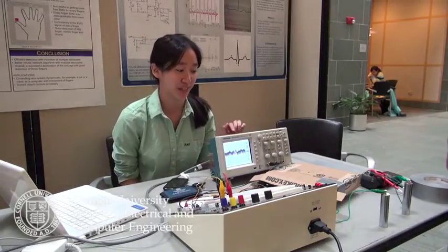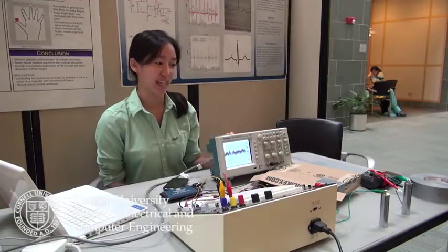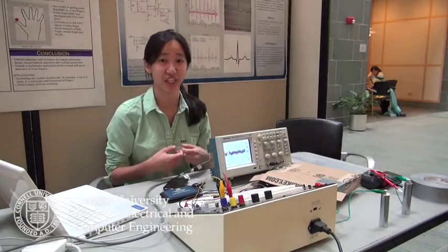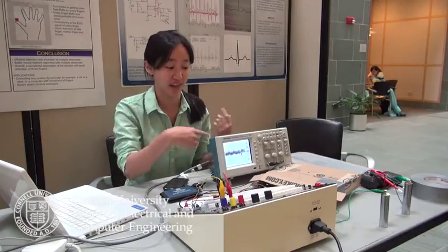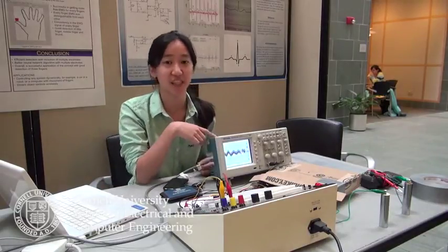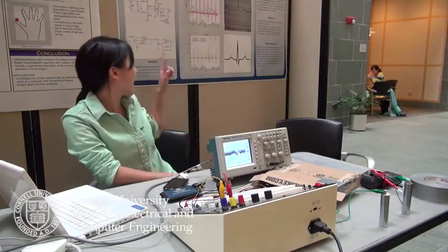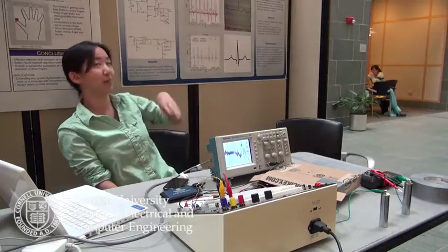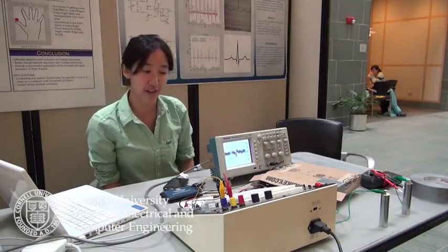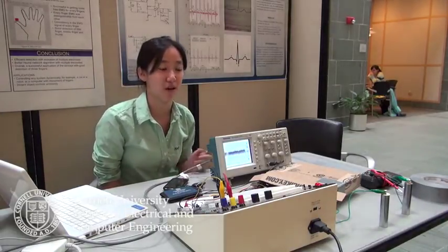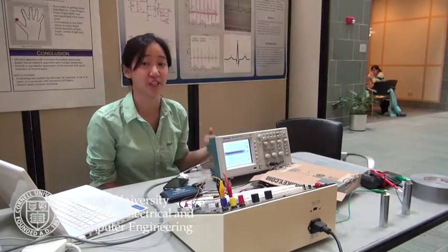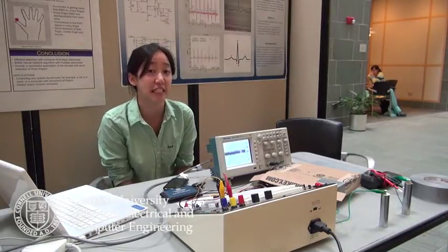And so what we did was we built a circuit that can, just when you touch the metal bars, calculate someone's heart rate and also show their beats on this oscilloscope. Our circuit is here, and it's completely safe. At the beginning of the circuit we have capacitors, which help with DC isolation, and resistors, which limit the current. That's our conditioning stage.